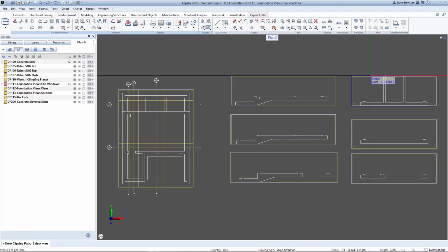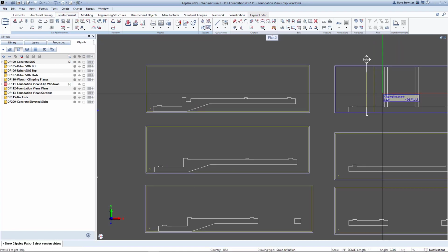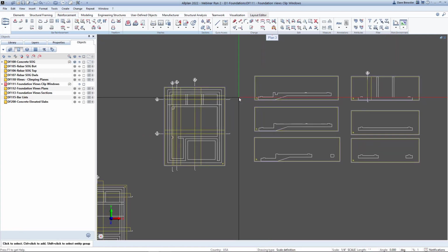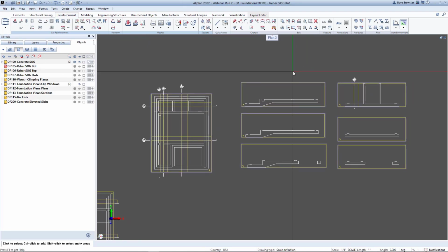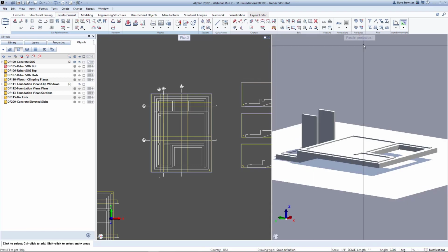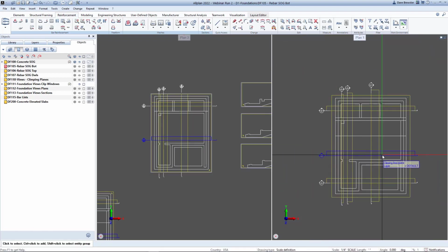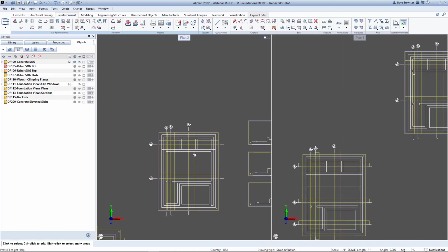What I'm going to do here now is these section cuts are able to be placed in other views. So, for detailing purposes, we want to show on the section view where that section cut is. We can simply highlight the section and say, I want to see it in this particular one, and we can choose which views and sections we want those in. So these everyday mundane things to just create the drawing itself, even before we put rebar in, the time is greatly shortened just by having the information pulled from one source object. So that's what generating the views and generating the sections and having automatic section updates, that's what it all means.